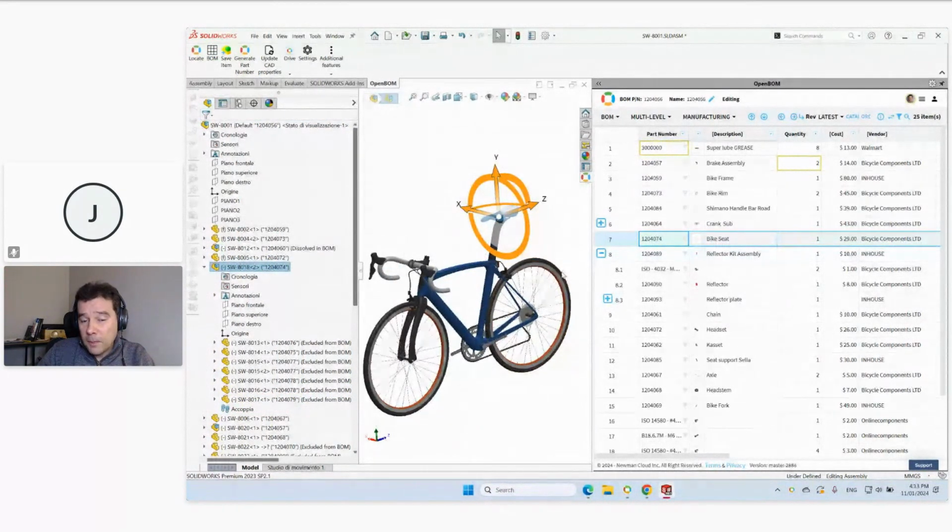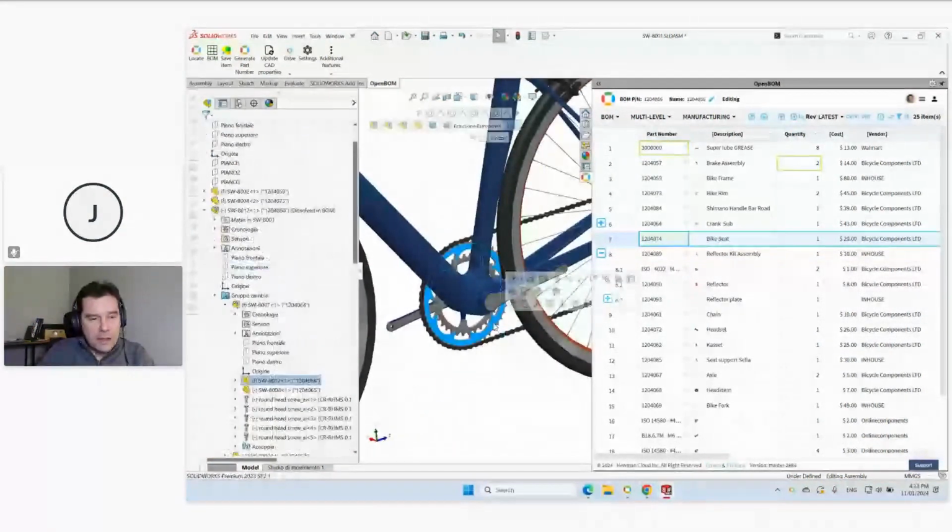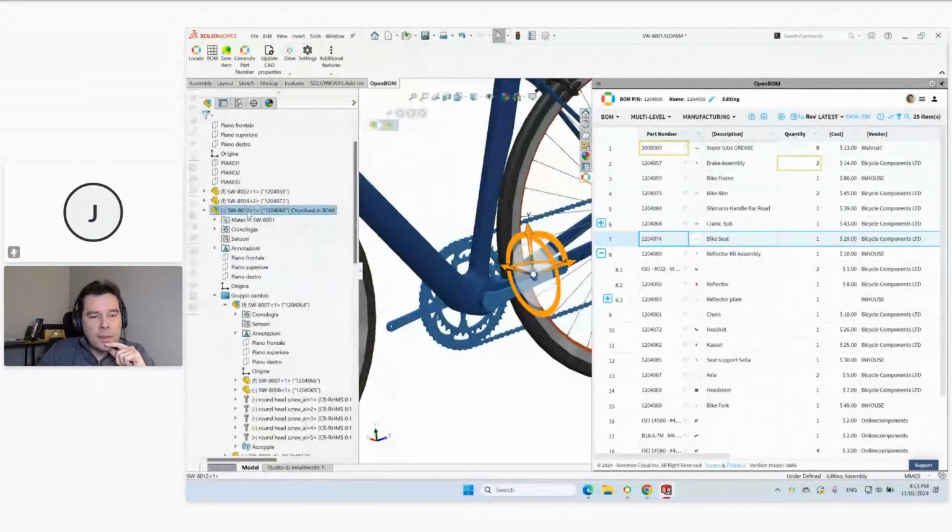Another example would be a phantom assembly. So I have another example where there's an assembly in SolidWorks that doesn't exist physically. Like this assembly here, you don't want to track it, you don't want a part number for it. It's just something that is for drawing only purposes. So we can also use the promote settings in SolidWorks to bring the correct level to OpenBOM. So most closer to a manufacturing BOM, or the bill of materials that you want to have and manage. So instead of moving to Excel and starting to remove this, you can work directly with the OpenBOM interface.